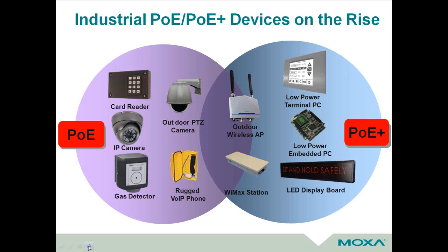Even though they say PoE, and it's a device that, like I had mentioned, might be a potential high-power device, you should check to make sure that it will work with a standard PoE switch, or if it requires you to use their proprietary injector that may not be industrial. In most cases they are not industrial. There are not many people that make an industrial PoE injector, or switch for that matter.